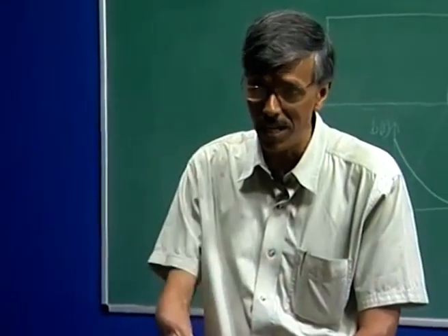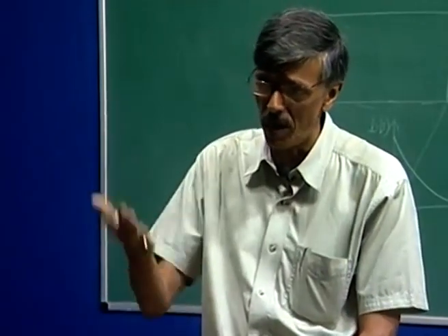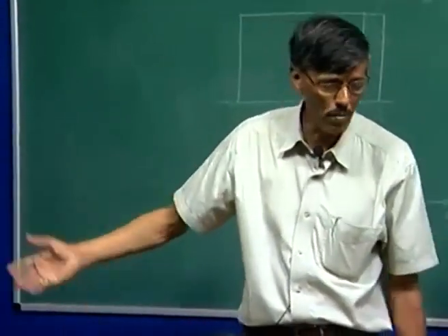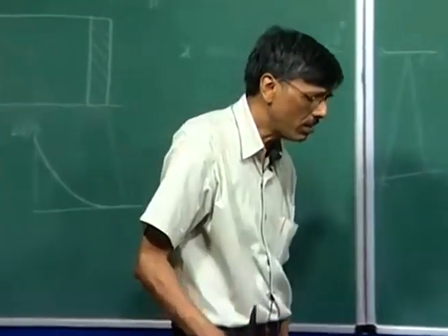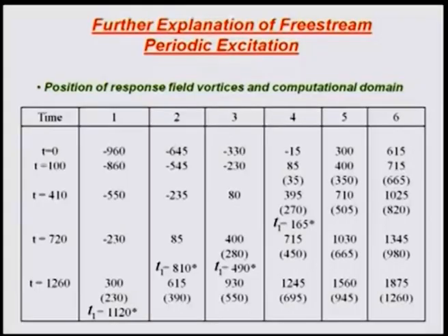This low frequency excitation will make the whole boundary layer breathe up and down. So, you are going to see a very, very complex flow phenomenon. So, in a sense, what we are hinting at here is that if we do go ahead and do these sorts of calculations, or you do the experiments, transition is virtually inevitable.